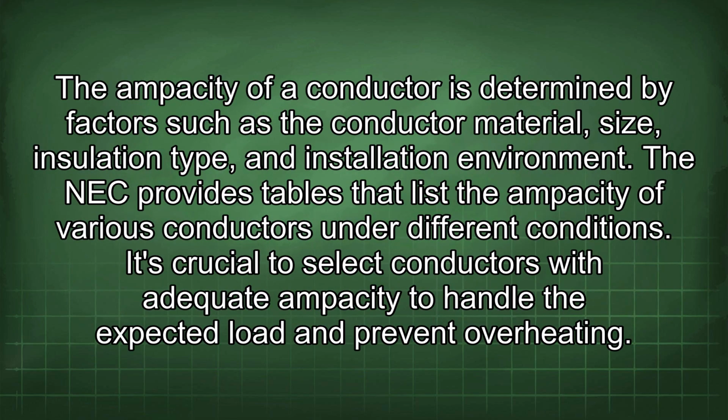The ampacity of a conductor is determined by factors such as the conductor material, size, insulation type, and installation environment. The NEC provides tables that list the ampacity of various conductors under different conditions. It's crucial to select conductors with adequate ampacity to handle the expected load and prevent overheating.